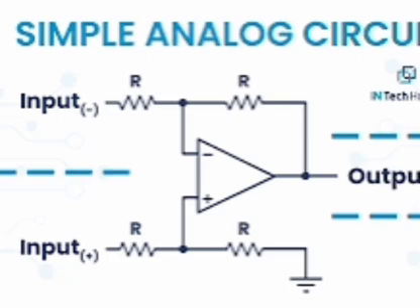Peak inverse voltage of half wave rectifier: Vm. Peak inverse voltage of center tap based full wave rectifier: 2 Vm. Peak inverse voltage of bridge circuit based full wave rectifier: Vm. Regulation percentage of half wave rectifier: Rs plus Rf by RL into 100. Center tap based full wave rectifier: Rs by 2 plus Rf by RL into 100. Bridge circuit based full wave rectifier: Rs plus 2 Rf in numerator, RL in denominator, into 100.